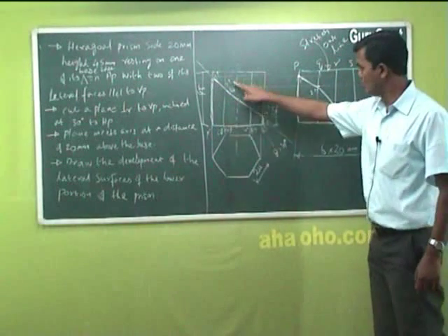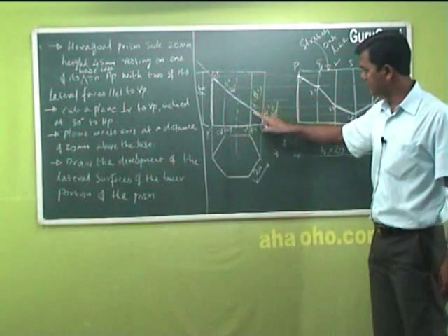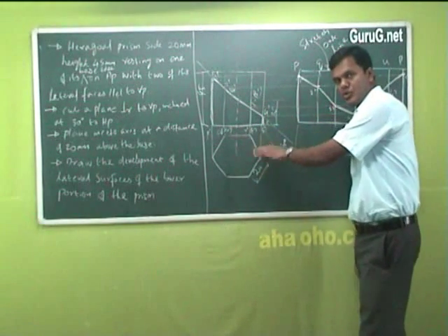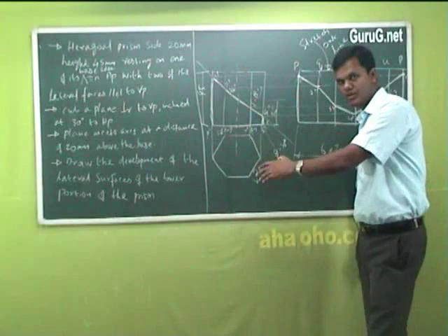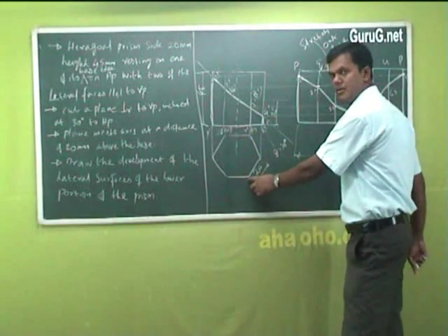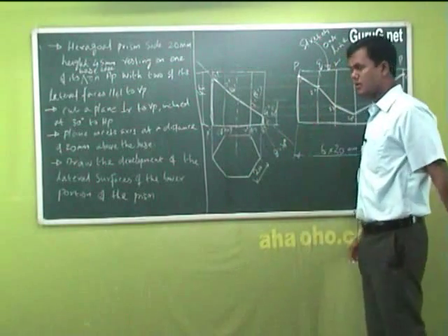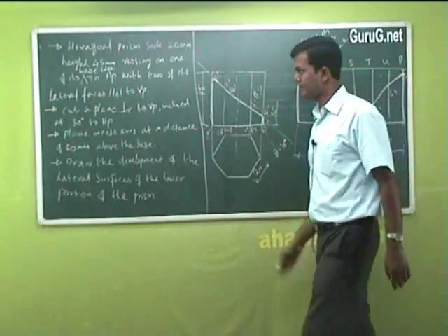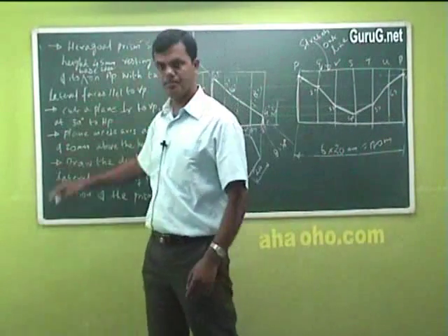Point P, 2 lies under point Q, 3 lies under point R, 4 under this. Again, this 4 is a corner, so you don't have another edge to cut. It's a corner only. So it goes under this one, you have the backside point, so that you have to measure. So 2 points you will get and finishing. That will give a complete development of your hexagonal prism.